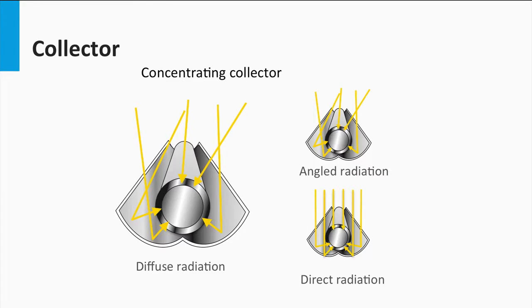The other shape that collectors can adopt is in the form of concentrating collectors. These collectors are for applications that need temperatures higher than those possible with flat plate collectors. Temperatures can be increased by decreasing the area of heat loss. This is done by interposing an optical device between the source of radiation and the energy absorbing surface. The small absorber will have smaller heat losses compared to a flat plate collector at the same absorber temperature.